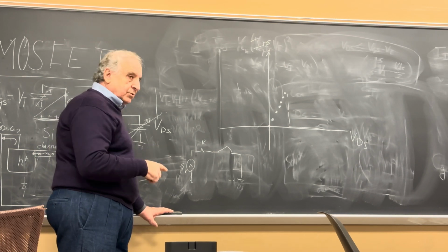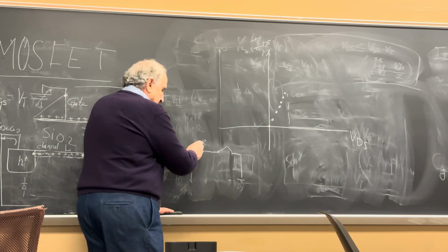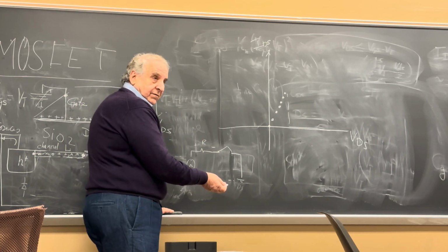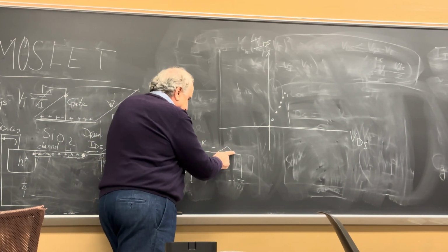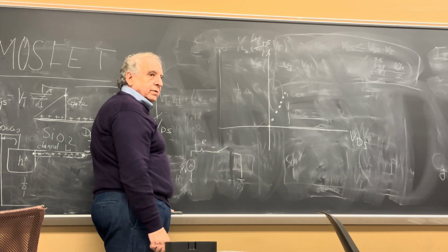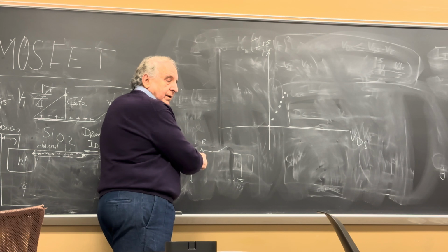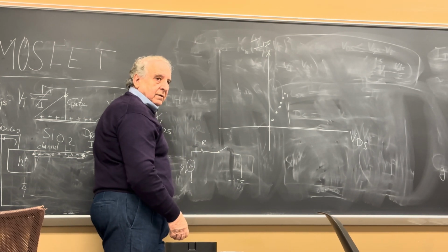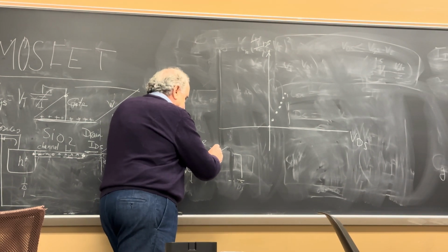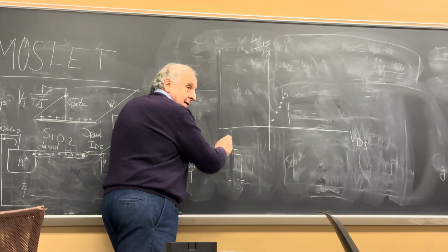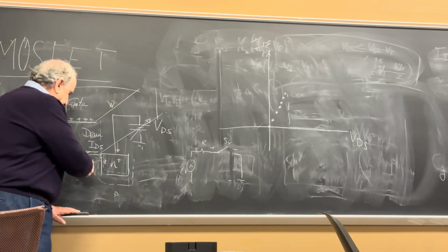The switch is closed. The resistor. Right there, right? The voltage goes here. Now, open the switch. Where's the voltage go? Stays. How much current will be here? Zero. So where's the 5 volt? On both sides. Where is the switch? Yep.